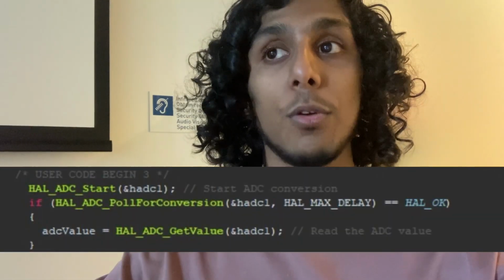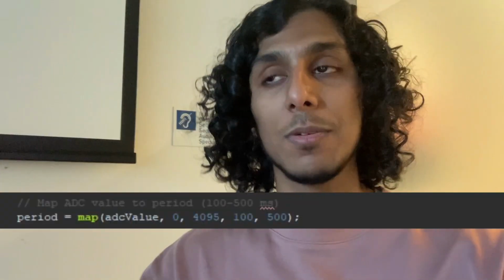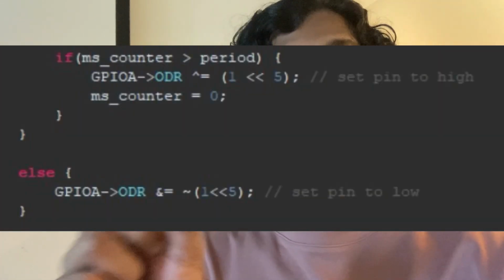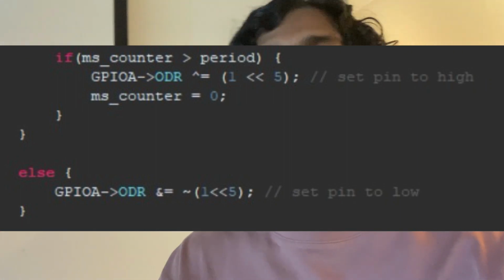And in order to do that, as you can see in the configuration, we configured ADC to in0, and this allowed for the PWM channel to kind of flow through. And that means that every time we turn the potentiometer, it changes the ADC value. And we can map that ADC value to the frequency needed for the LED, and you can see that there. So with this mapping, we can then specify an integer called period. This period is basically the time that it's off or on by. So 500 milliseconds will correspond to 5 hertz, and then 100 is 1 hertz. And so we vary the potentiometer reading. As we turn the potentiometer, it'll then vary the frequency.